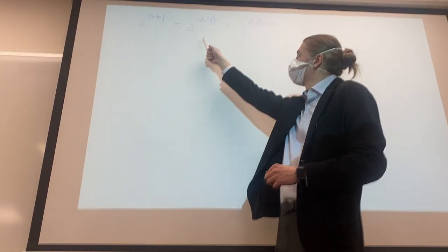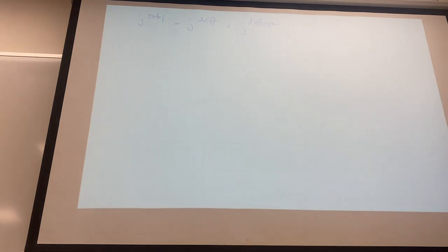So when I said that if you're not applying a voltage, drift current is 0, that is true unless you end up with a voltage that gets applied intrinsically inside the device. And that is one of the hardest things to imagine in diodes when we have a p-type and n-type device next to each other. First, you get diffusion. First, there are lots and lots of holes on one side and none on the other because you've got a p-type material over here. And then there are lots and lots of electrons over here and none on the other because you've got n-type material over there. So the first thing that happens when you bring these two p and n types together is this rush of electrons from one side into the p-type material and holes from the p side into the n-type material. So there's this huge initial diffusion current.